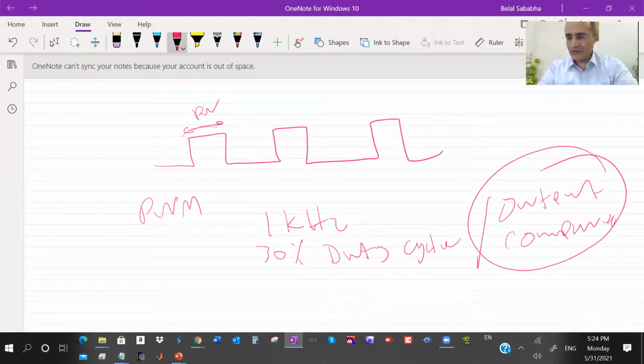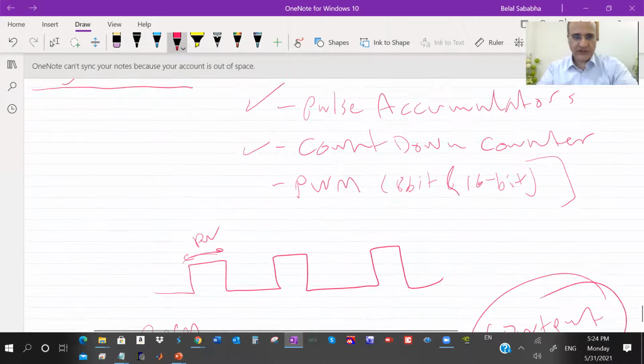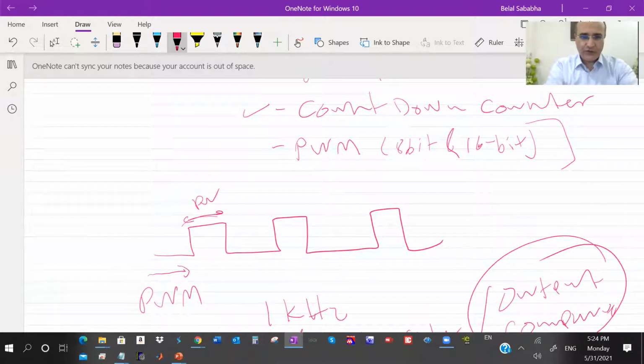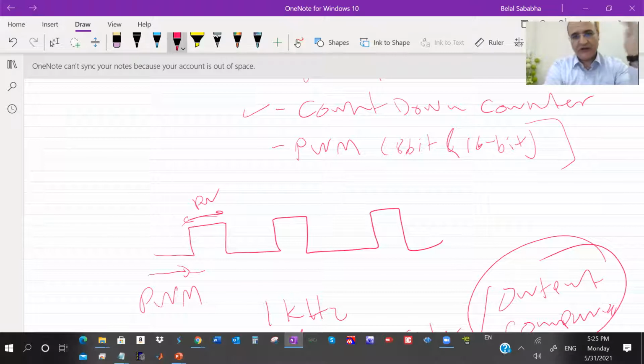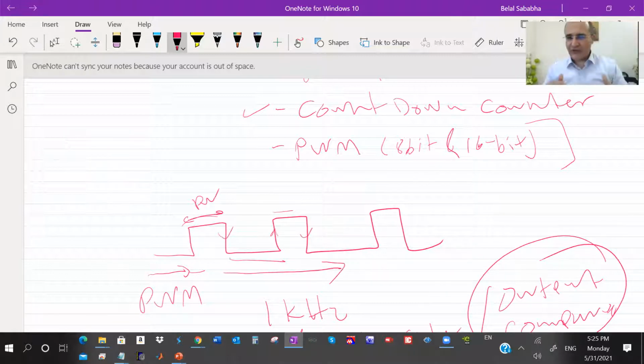However, if you look at the code we wrote last time, we were moving along with the signal. Did we reach this? Okay, next time you go high. Oh, okay, now we're high. Next time, write the compare value register again and tell it that when the match happens again, next time you go down, then give it a new value and tell it next time you go high, and so on. So it implies a lot of overhead to program PWM signals with output compare.